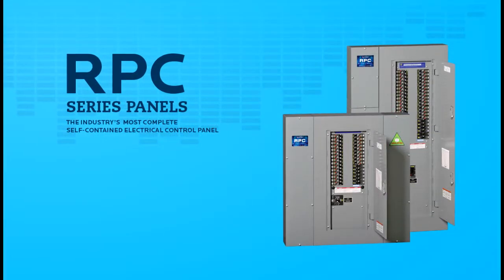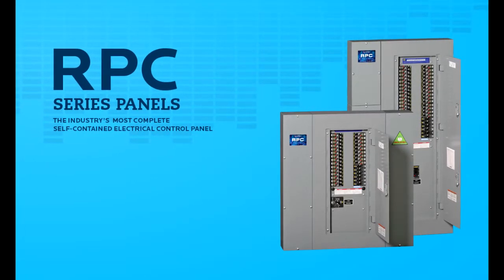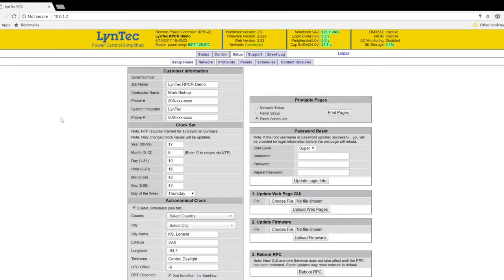That's it for the basic setup and operation of the RPC software, but additional settings and features are available. On the Setup Network page, you can set the LAN settings and external control protocol options. On the Setup home page, job information can be stored, clock settings changed, the default password changed, and you can print hard copies of your setup for archival purposes.